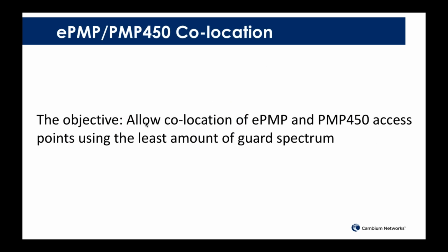The first thing that very few customers know, when I talk to different customers worldwide, is that right now you can do the collocation between ePMP and PMP 450. So if you have collocated sectors with CN Medusa or with 450i or with any other 450 product, you can collocate it with ePMP, meaning that you can do the GPS synchronization and you can do the frequency reuse between these two different platforms.